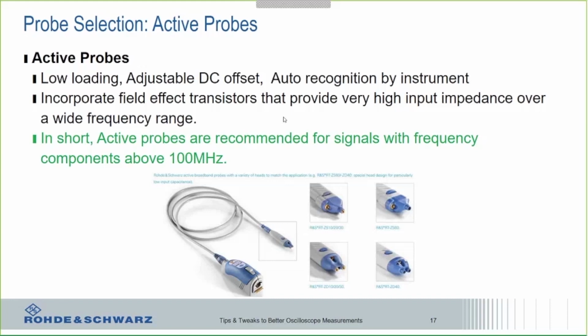Now, of course, the drawback to an active probe is that they are typically an option, and they are going to be more expensive than something like a passive probe, because they have a lot of capability built into them. But just know that one of the benefits of having an active probe is seeing that higher frequency content and not having as big of an impact on your device under test.